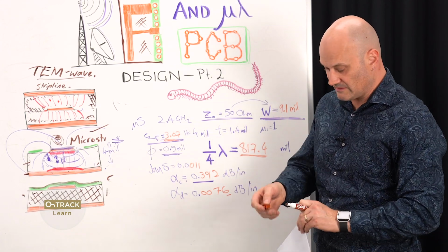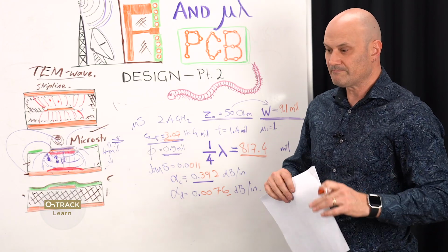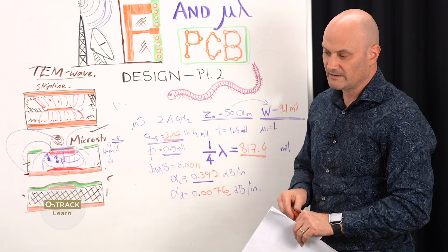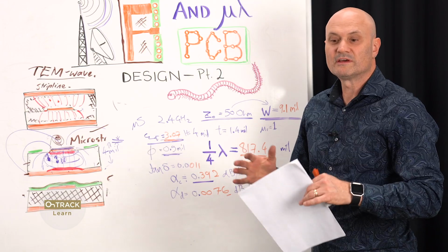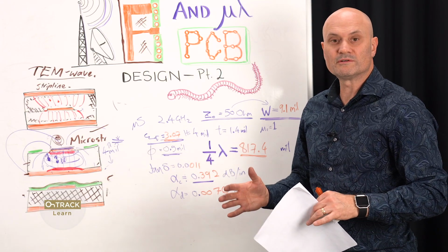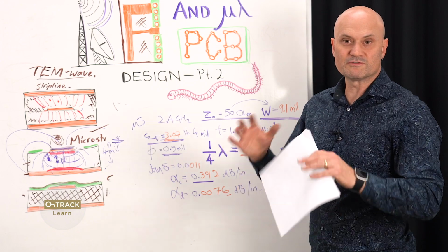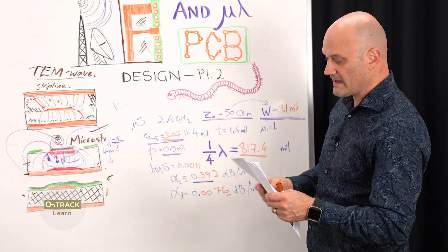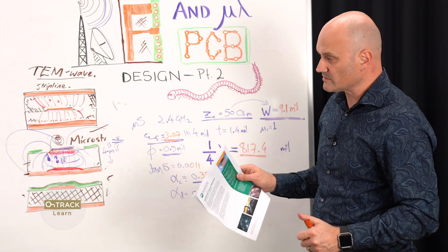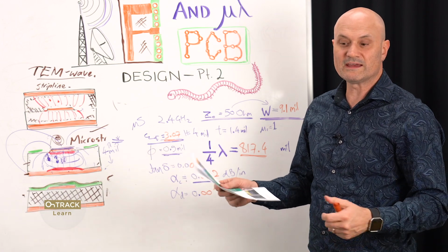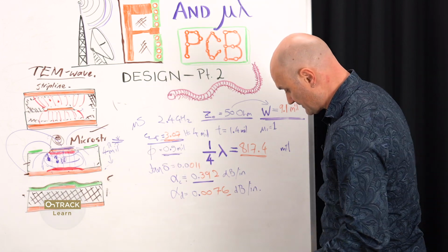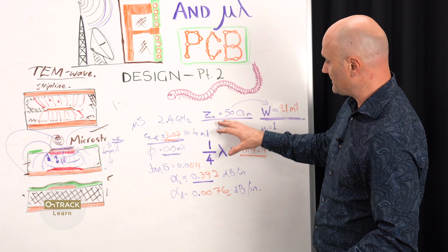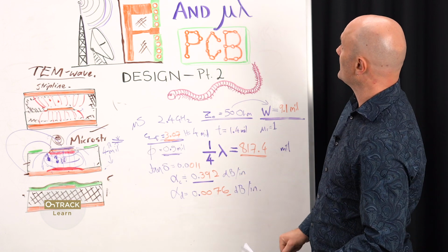But if you need to do some huge antenna array or some board with a lot of mixers or directional couplers or splitters and combiners on a board, then your losses are going to become a problem because your feature sizes are so much bigger, and you need to pay attention to that. So in that case, use a good low loss material. It will cost more, but your product will perform, and that's the only way to get in spec sometimes. So that's just 2 examples of what we do to calculate the impedance and then figure out what kind of material we want to use.